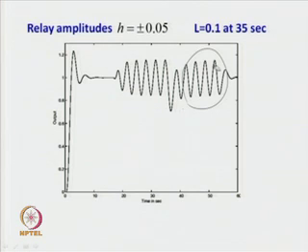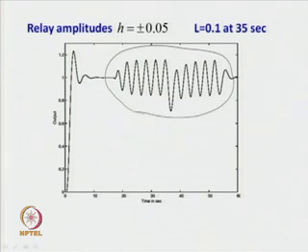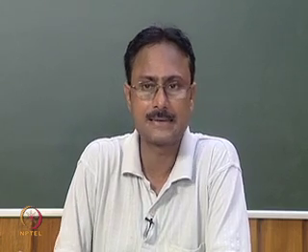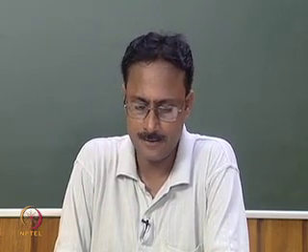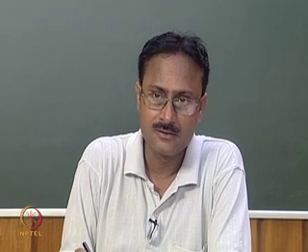So, if we carefully observe, when the relay is withdrawn, then also we are going back to the steady state condition. Therefore, the effects of static load disturbances are successfully rejected. So, the limit cycle output is not affected by the static load disturbances.